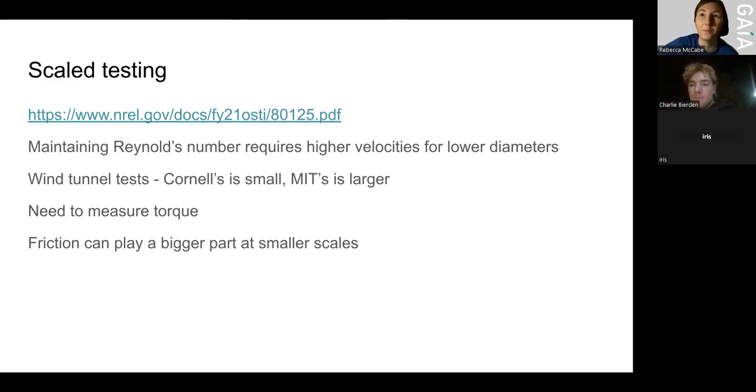People have often brainstormed the idea of, oh, can you put the blades on a car, strap them to a car and then drive the car at speed so you can get whatever speed you want, controllable, without the facilities or effort required with a real wind tunnel test. And so that is a possibility. Sure, you can do it. It's just difficult to get the right quality of data because if the turbine is strapped to a car, the car is going to mess a lot with the airflow.